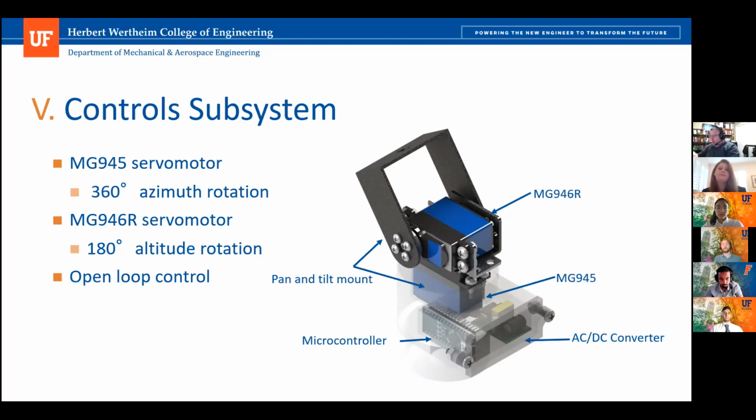A bearing is incorporated to the non-driven side of the bracket to provide support and reduce friction. This bearing is internally lubricated and externally sealed. The aluminum servo adapters transmit power from the servo motor to the brackets. They are anodized clear to increase corrosion resistance.